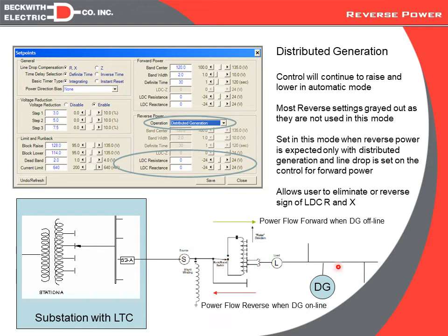So with that in mind, we can do one of two things if we select DG. Number one, we can have our plus 4 in the forward and just have no compensation in the reverse. Or if we still want to cover that 4 volt drop, since this is still the device regulating, we would actually put a minus 4 in the reverse direction. And if we had a minus 4 here in the reverse direction, that would cause it to raise 4 volts here to keep that end of line circuit voltage up.